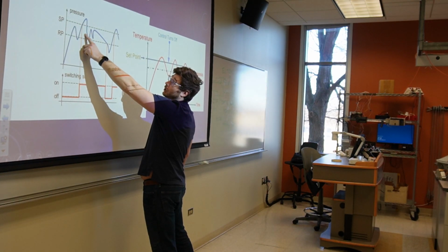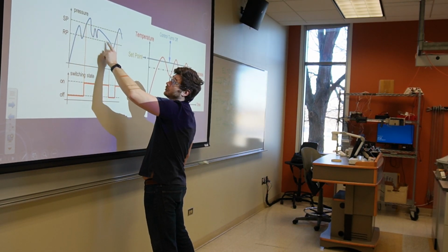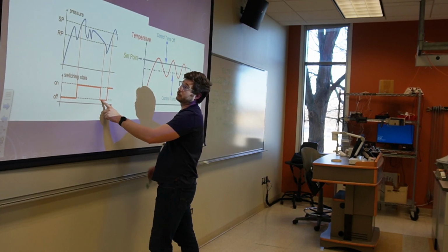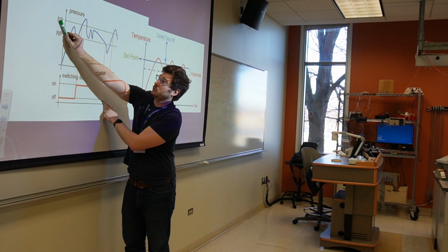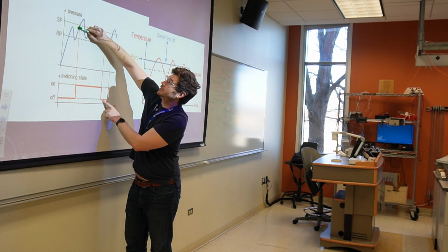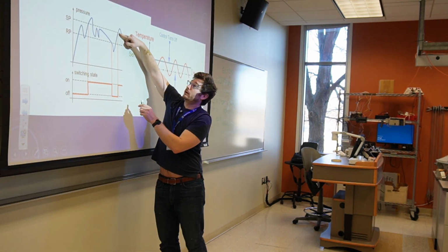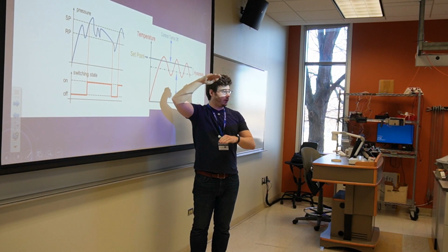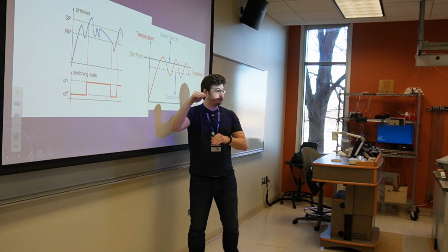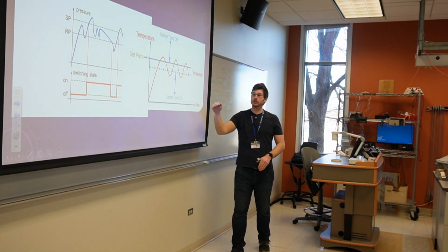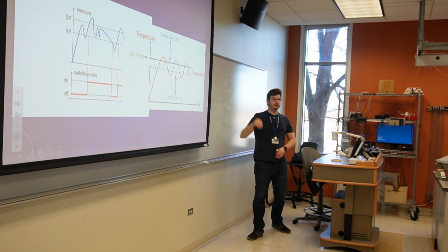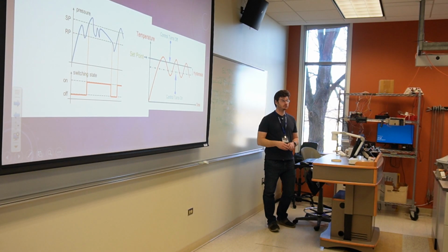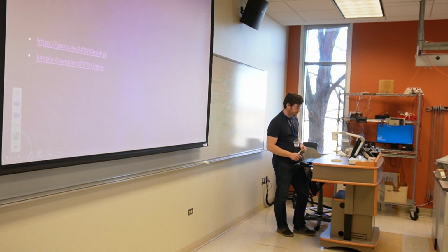Then it would have to lower again underneath this threshold before we will turn off our output, right? So this becomes a dead band. Anywhere in this region, it could go up and down and bounce all around all it wanted. We still know that we're where we want to be, more or less, right? Our control system should chill out. It should wait for it to come down until we pass that again, and then we can turn it back on. Hysteresis. Any questions? Cool.